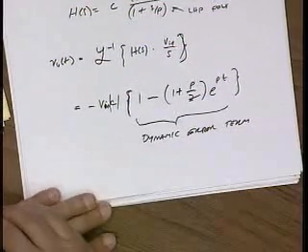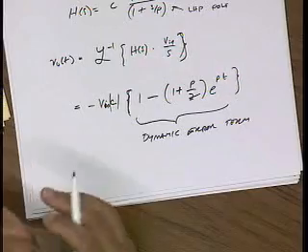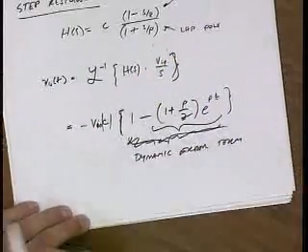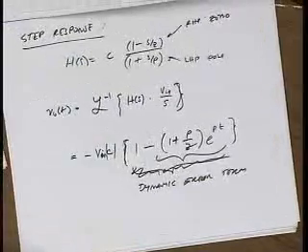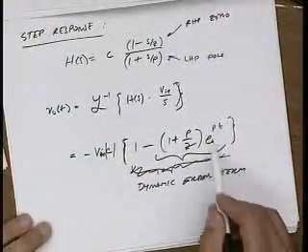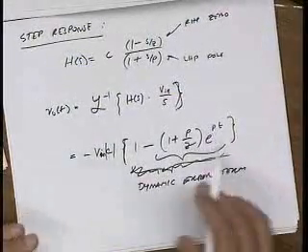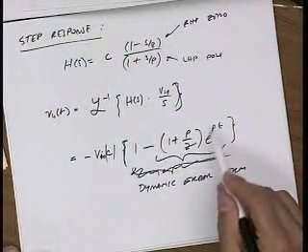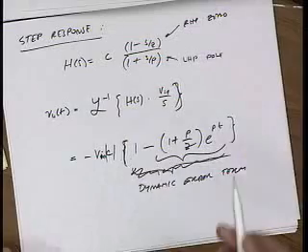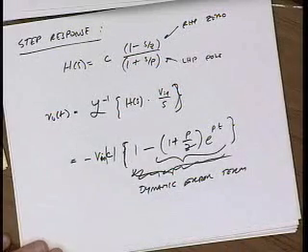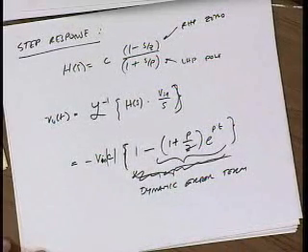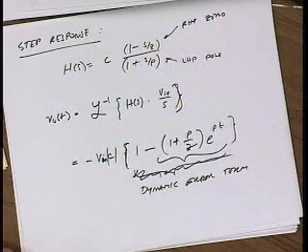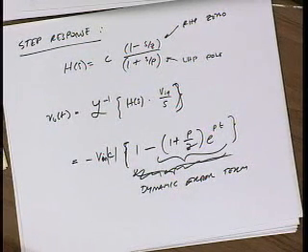If you wait infinitely long, what happens to the error? Let's say this is the error term here. Oh, it goes away because this pole is in the left half plane, right? So if I wait infinitely long, this term goes to 0 and I have no error. So looking at this equation, can anyone tell me a good strategy for picking your poles and zeros?